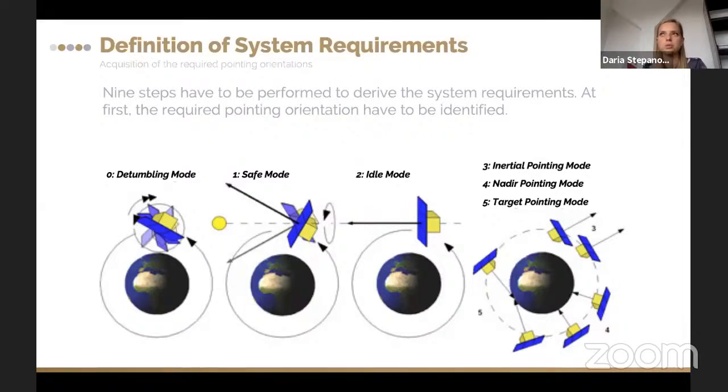We're normally using 2 UHF modules to provide the full sphere coverage on the satellite. That's used for telemetry and telecommand. If we're talking about high-speed communications, S-band or X-band transmitters are the most common. There are a couple of projects which are using K-band.